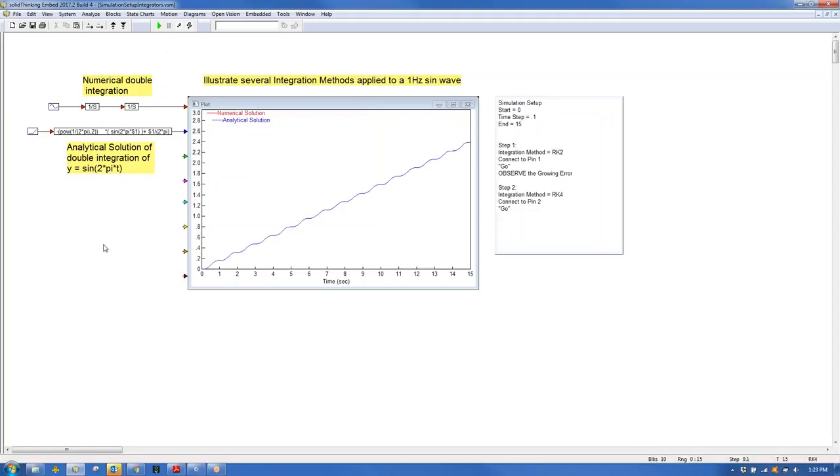This example that I have here kind of shows you what different integration methods can produce. I have a numerical integration up here on the top, so I've taken a sine wave and double integrated it. And if you look way down here in the bottom right corner, this little information at the bottom of the screen, the last thing tucked over here in the corner says RK4.